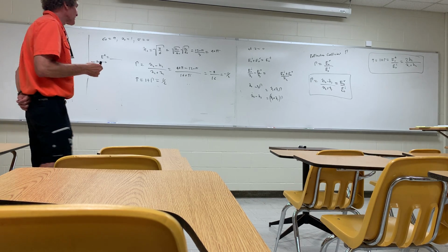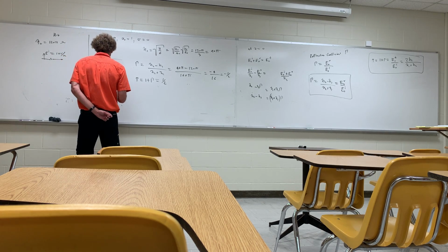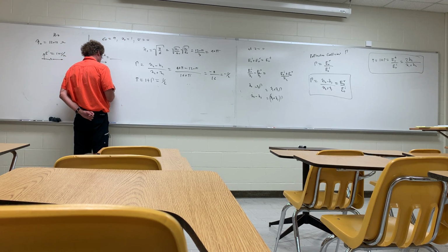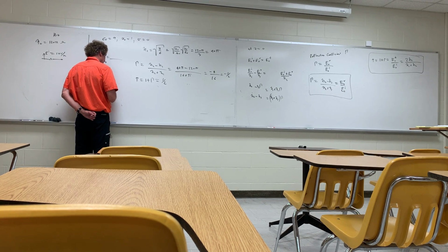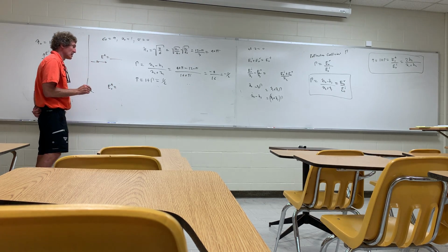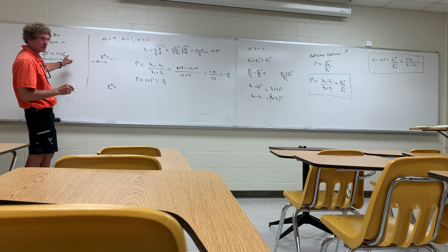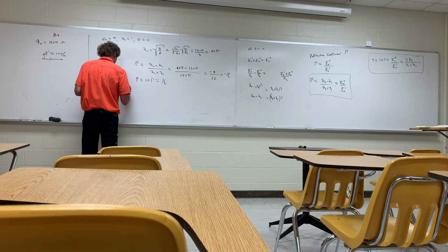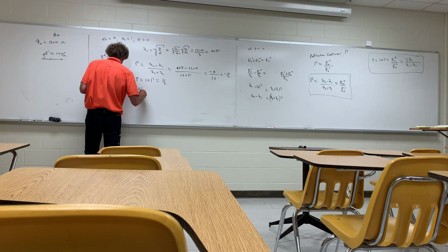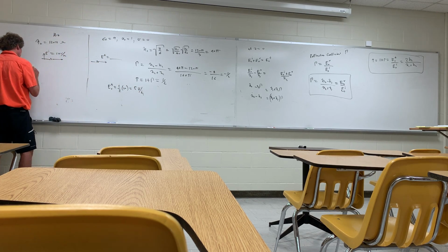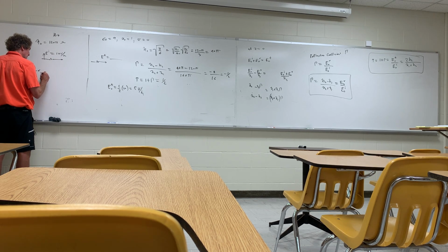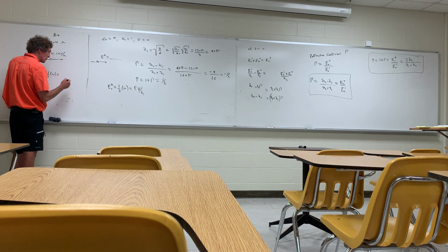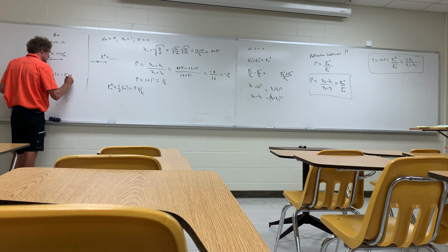All right. So therefore, what's the magnitude of the transmitted field? What's E transmitted? 1/2 times 10 volts, isn't it, class? Right. So it would be 1/2 times 10 volts, or it's equal to 5 volts per meter. What's the reflected field? Minus 1/2 times 10, or the coefficient would be minus 5 volts per meter. Correct, class?